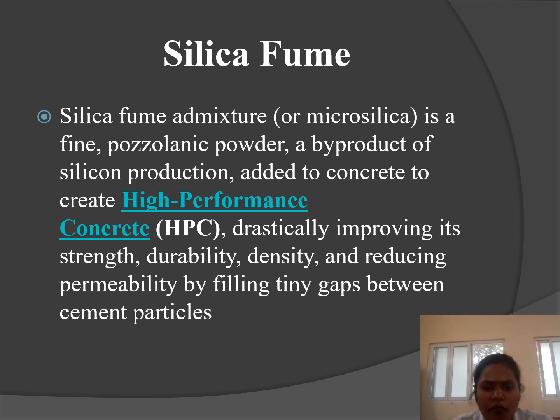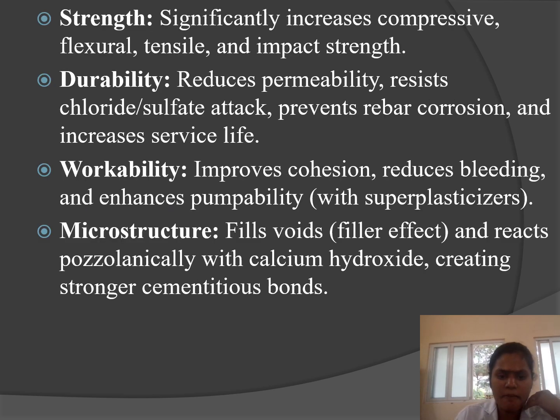Silica fume. Silica fume is an admixture, a fine pozzolanic powder, a byproduct of silicon production, added to concrete for high performance concrete, drastically improving the strength, durability, density and reducing the permeability by filling tiny gaps between cement particles.